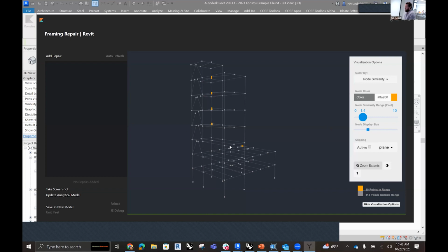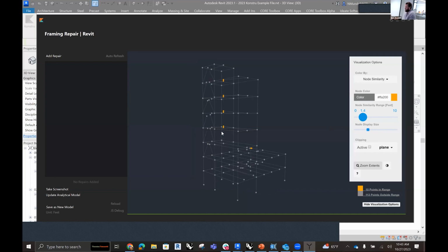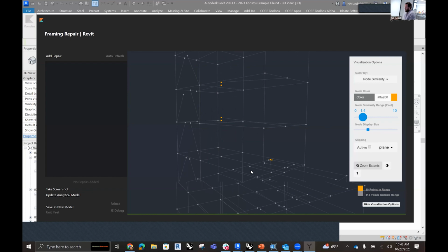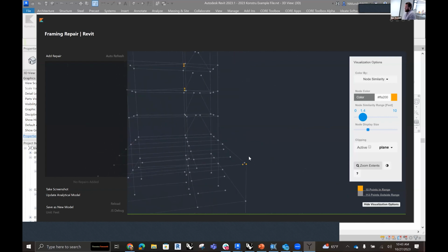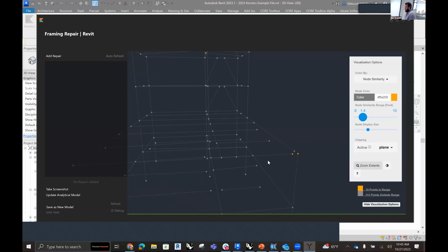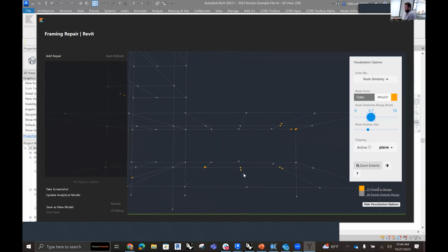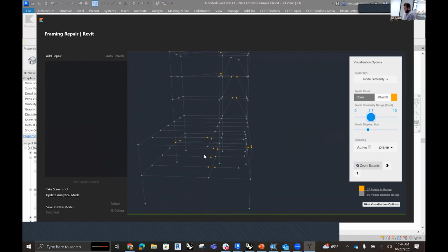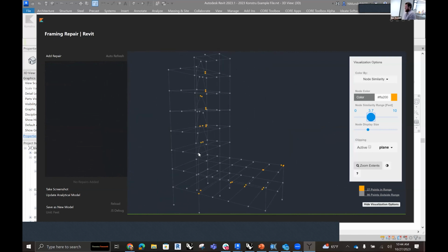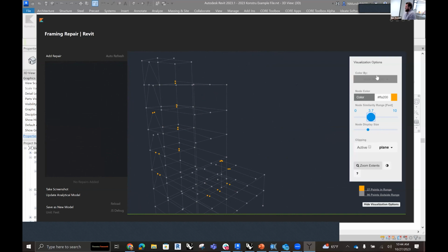So at the moment, every node that is within 1.4 feet is being called out. So some nodes are going to be red naked nodes, easy to discern. This can be a nice way to find out where there are nodes that are close together, but not quite connected, and what distance those nodes are from each other. So just an interesting way to review the model.